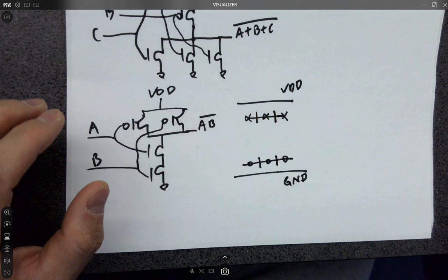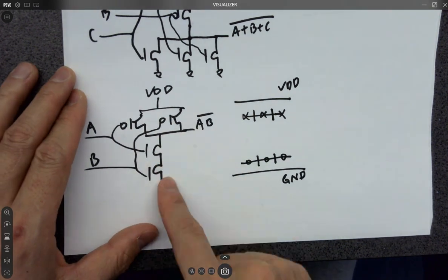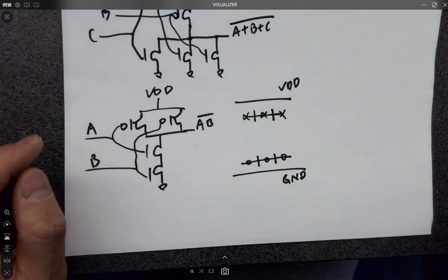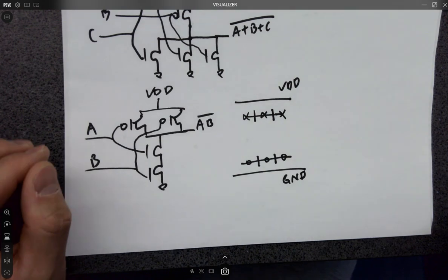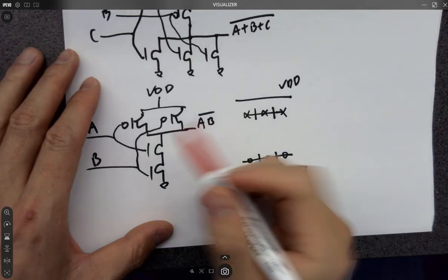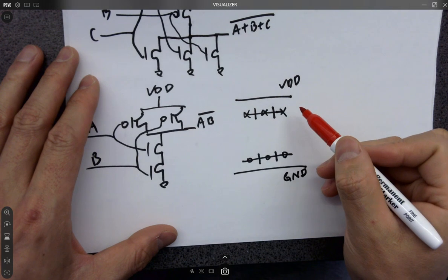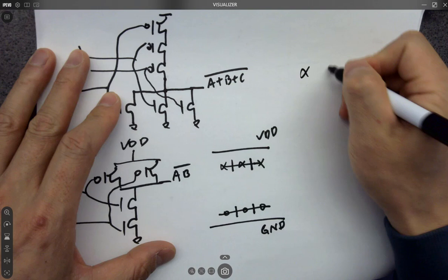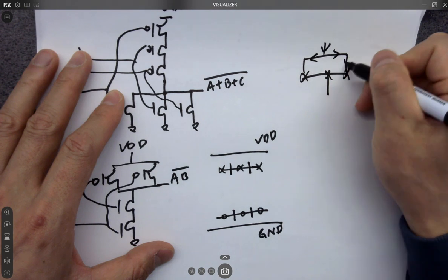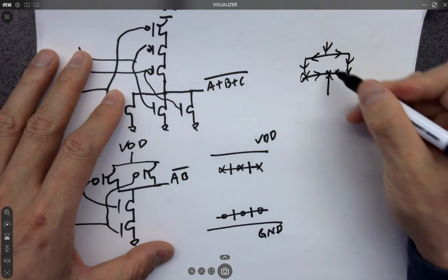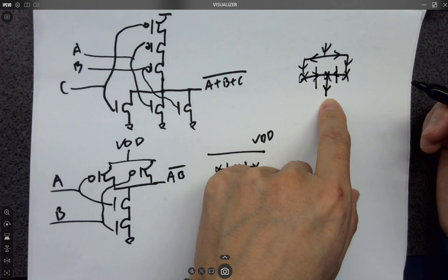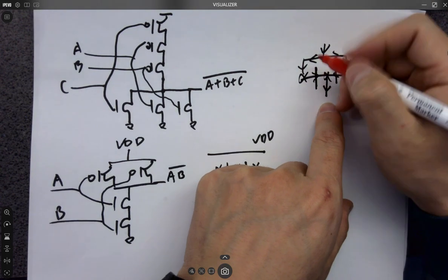And you're asking, hey, these are in parallel and these are in series. How could you do the same? How do you just connect all the nodes in a line? Because we can modify the metal wires in order to make them either in parallel or in series. And this is how we do it. So how do we make them parallel? Like I said, there are two ways to do it. You could either do this, so current flows and splits and merges and comes out from this metal. And these are gates. Keep in mind, these are gates.